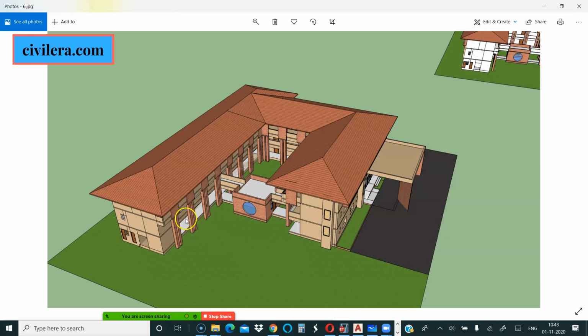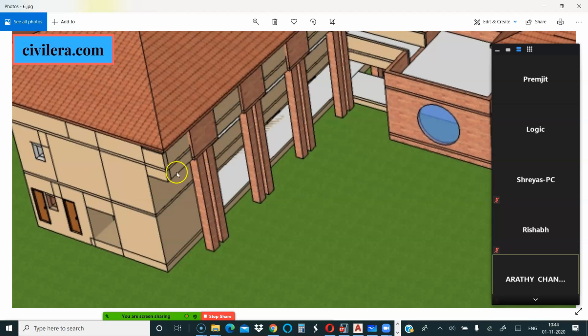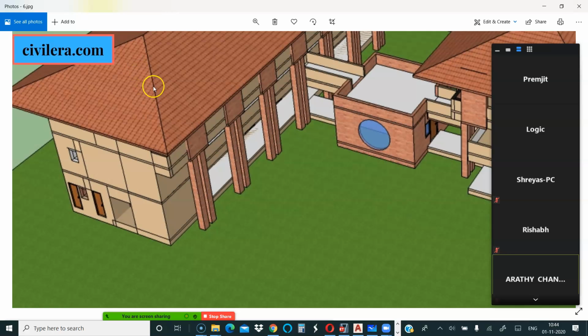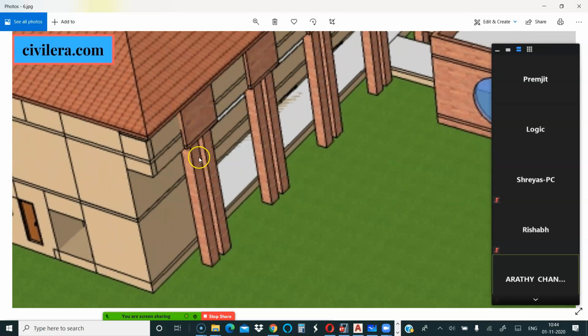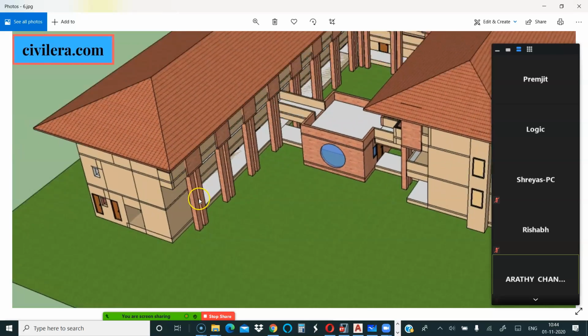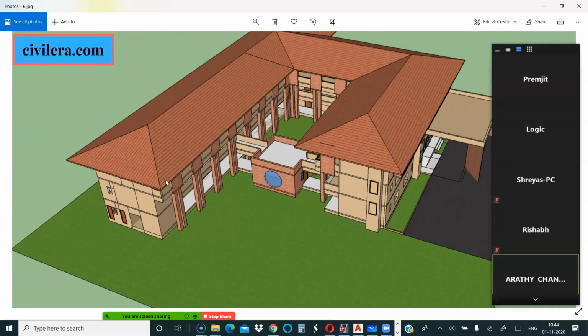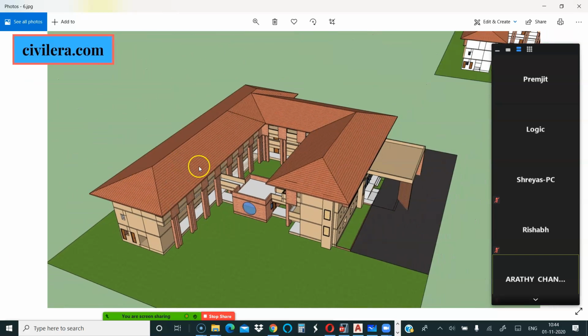It has two purposes. One, it's a shock column, and the last level, if you can see here, is cantilevering out and getting connected to the column. So the last level is projecting out, and the column takes that load. So the sloping roof, all that is supported on the twin columns. Otherwise, the lower level is not supported on the columns, and it is all cladded up to have the required finish. So that is the requirement, and I already showed you the plans.